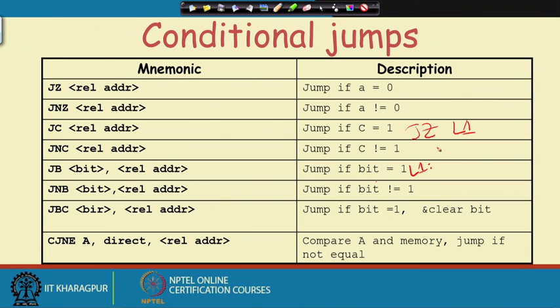If you have to make a really long jump, you put one LJMP L2, where L2 is far away in the program. By a small conditional jump we come to this point L1, and from that L1 we put a long jump and come to L2. This may be one way out, since these conditional jumps cannot be long jumps. They are all relative and short jumps.